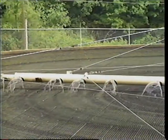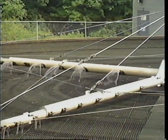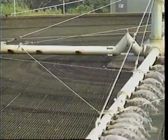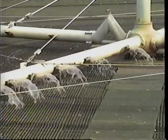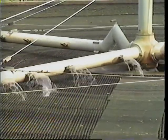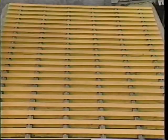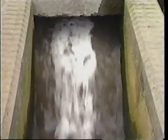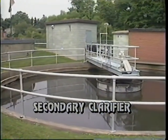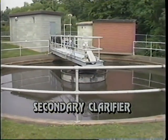Multiply rapidly and consume lots of oxygen, but they get it from the air rather than from the dissolved oxygen in the water. Eventually, the layer of feeding organisms will thicken and begin to break off and become suspended solids in the trickling filter wastewater. This is called humus or sloughings. The effluent from the trickling filter is then sent to a secondary clarifier, where the humus and other remaining solids will be settled out and removed.